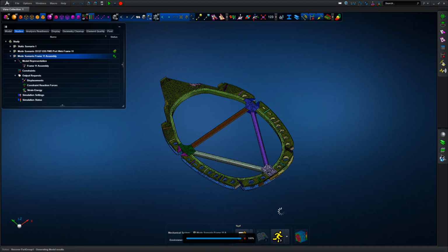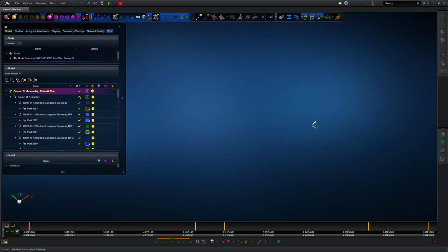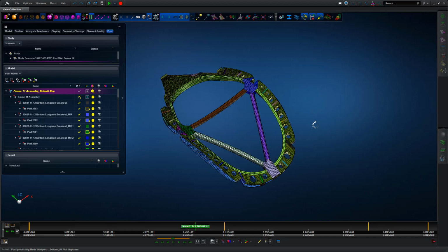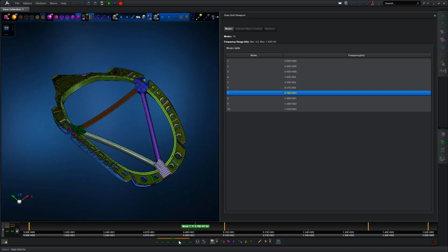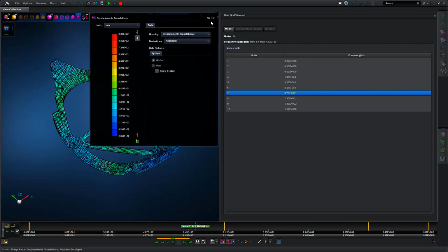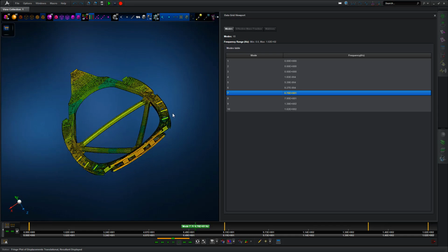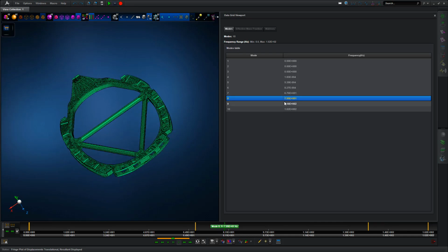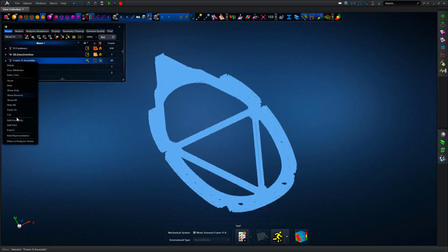So if we wanted to, we could go through each discrete part or sub-assembly and verify on their own basis, and then when we bring them together, the analysis time is far increased over a raw analysis, as it were. So again, looking at the elastic mode response, so mode 7 and above, so modes 1 to 6 are rigid body modes with very low frequencies, and so looking at the mode 7 response, and again displacement, we can look at strain energy as well as a further check, but we're pretty happy with that definition. Everything's tied together, and the structure's moving with a clean definition, as we'd expect.